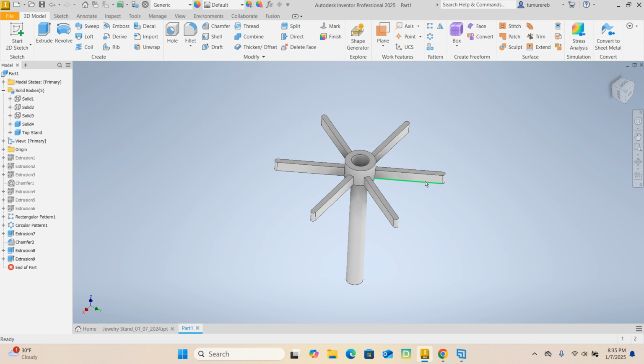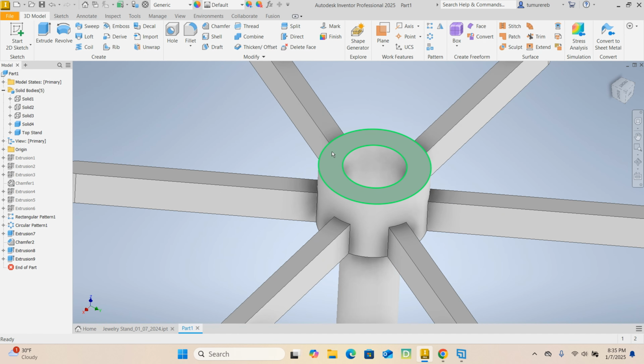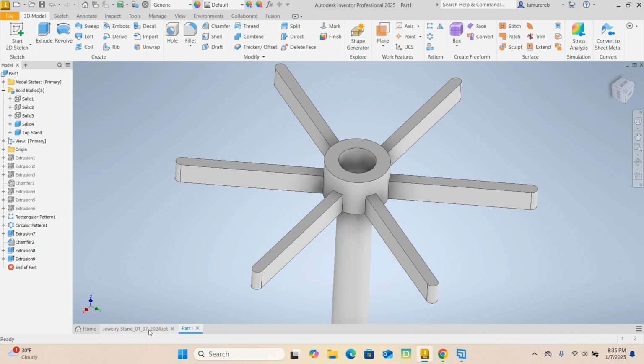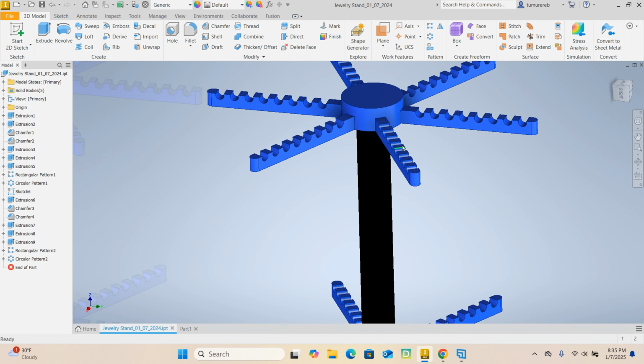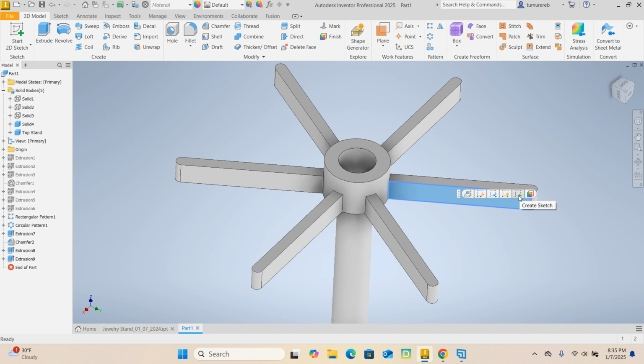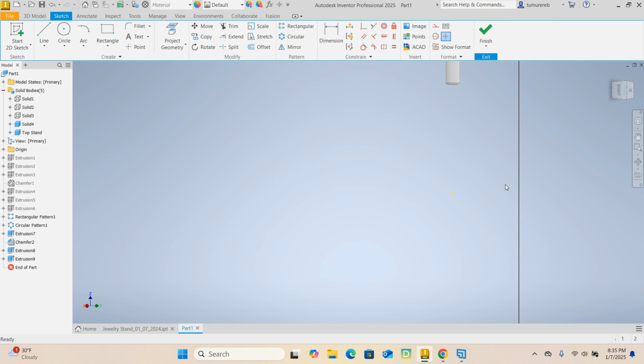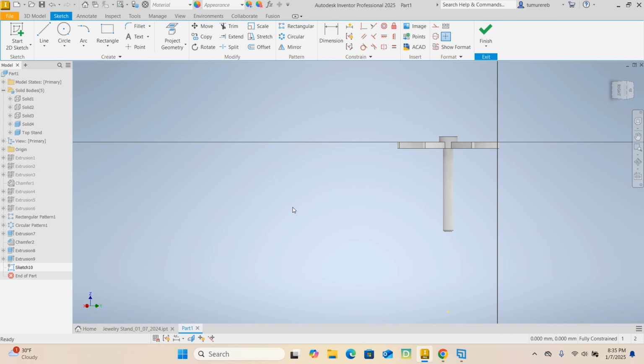All right. Okay, let's do one last thing. Actually, 2 more things. We still have to do this part here, like we did before. So you should be able to do this on your own. So I'm going to go very quick here to the sketch and go down, slice graphics. What did we do? Drew a circle about here.